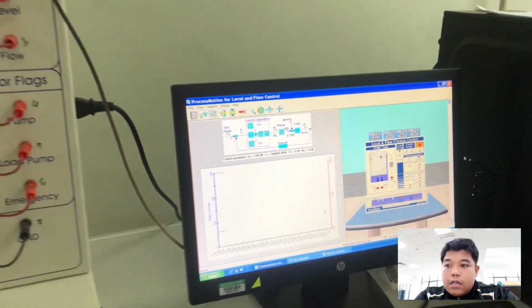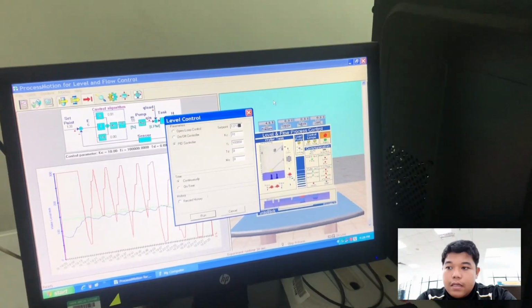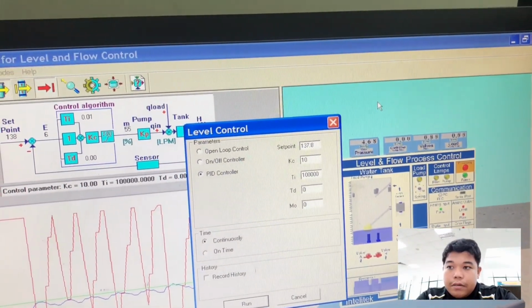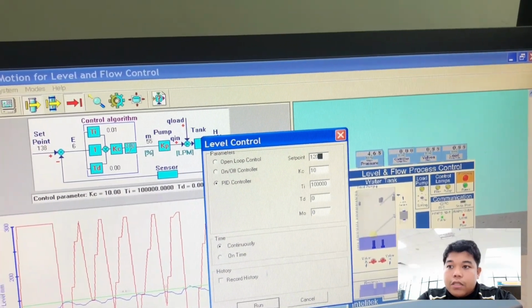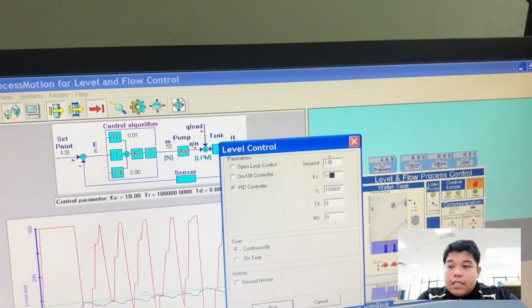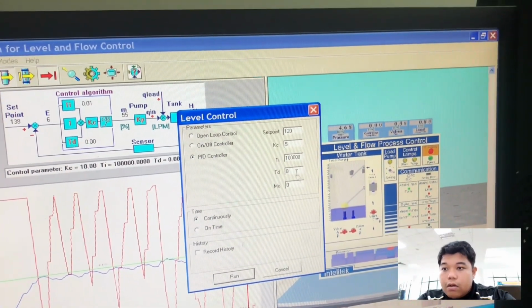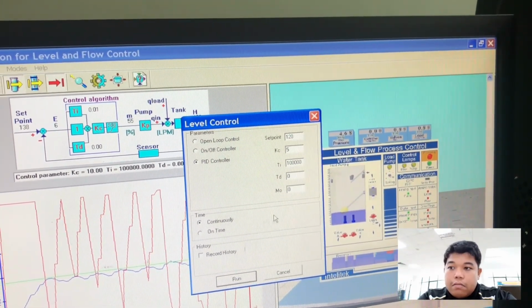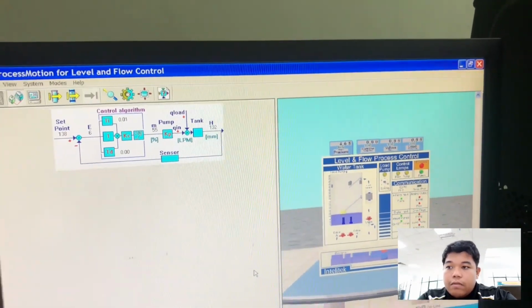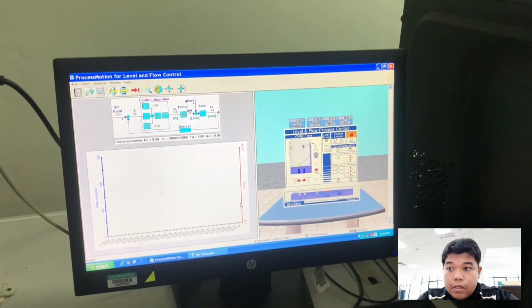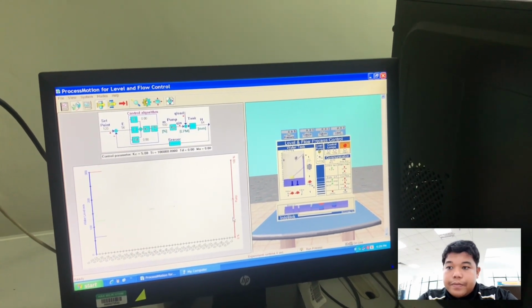Click run to see the response of the system. Run the system until it reaches steady state after 80 seconds, and analyze the graph shown to see the offset. The system output H is measured and recorded in the chart on the worksheet, and the column is marked until the reference value. For every row, record the controller output M in column 5 of the chart on your worksheet.